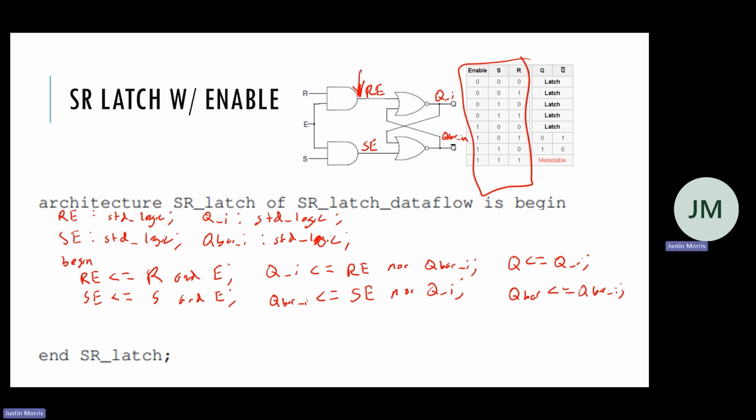If you have two zeros. So when you make your test bench, define some initial values for the inputs. You can just have your first test be reset to make sure that it is 0. And then your second test can be maybe the 0, 0 case. In that case, it should just output the previous one, which was 0.